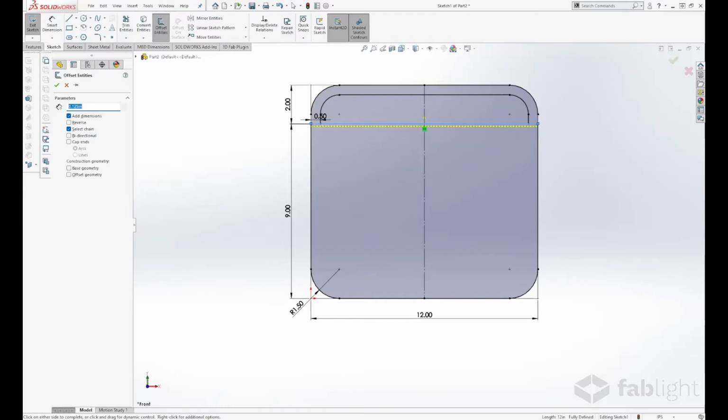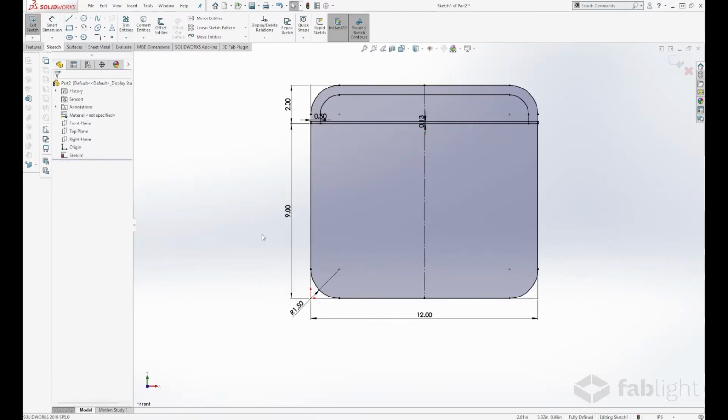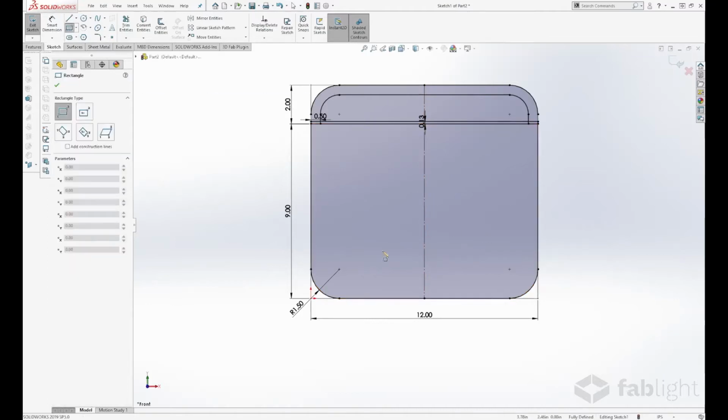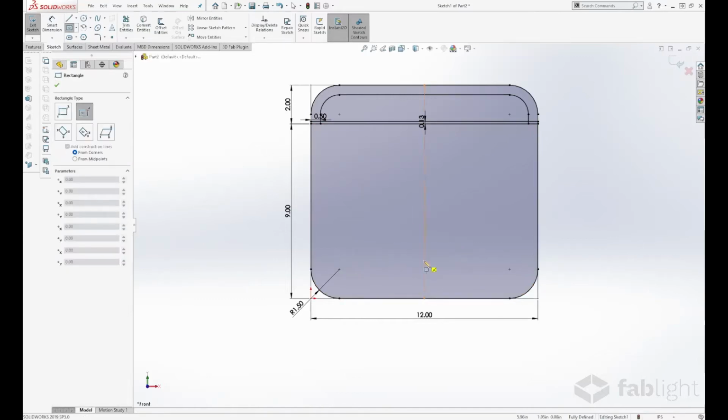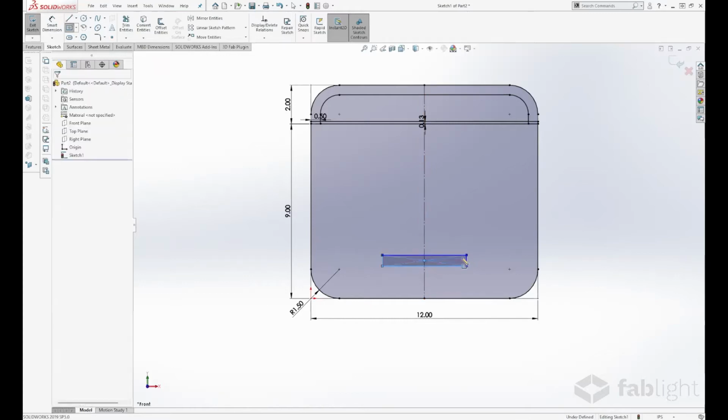So I'm going to do 1/8 inch to represent that. We're going to reverse that, so that's offset there. Now, the next piece we want to cut or create is a slot here. You may have seen it. It's for our crossbar. We want to create this slot here in the middle. What we're going to do, take a couple of rectangles, and actually we're going to change this to a center rectangle. We want this right off of that center line.